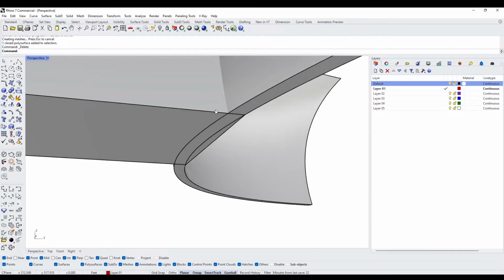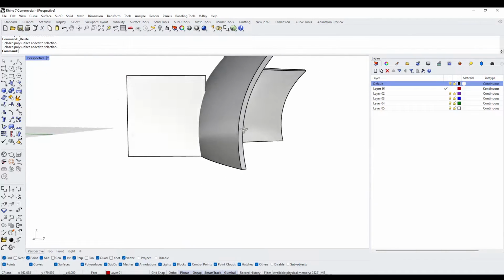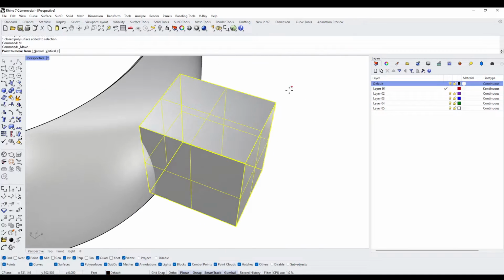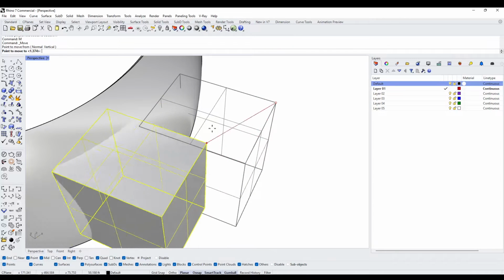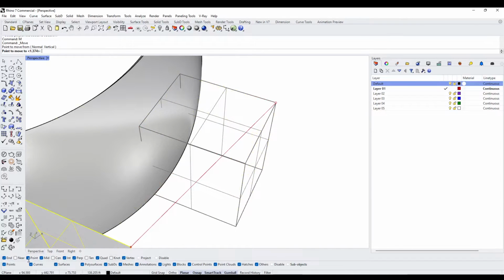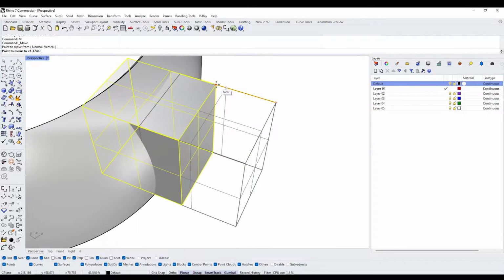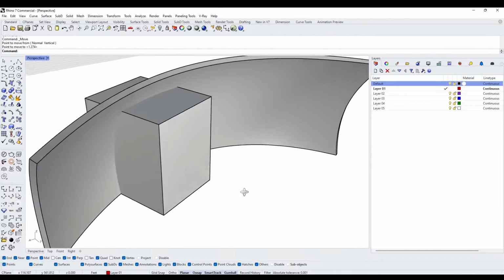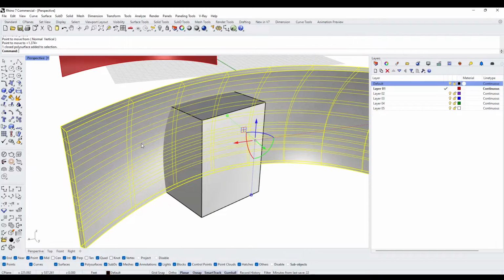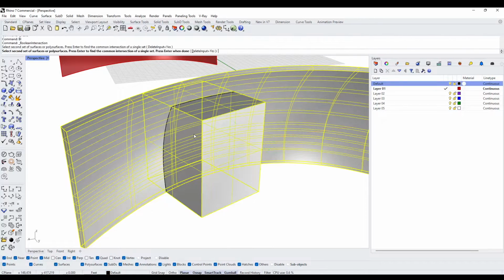Because we want these two to be on the exact same plane so they intersect perfectly, and so the door is easier to create. And that's because you wouldn't ever have that scenario happen in real life. Typically when you build walls, you're going to build them exactly on a plane or something, or if that's not the case, then it would be fairly rare. So we'll take this and we'll do the same thing. So select this, copy to clipboard, Boolean difference, this, paste, Control V, and then Boolean intersection, this.